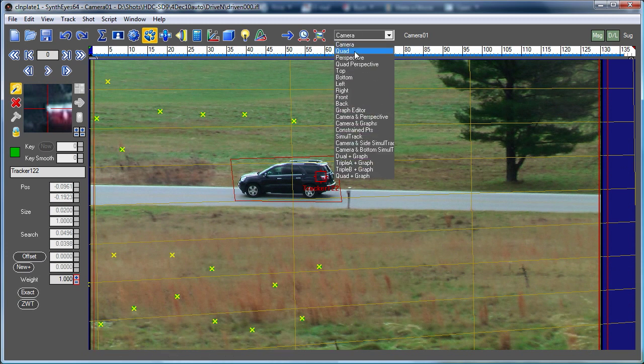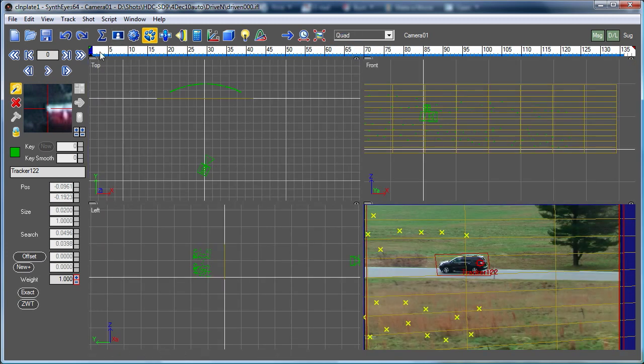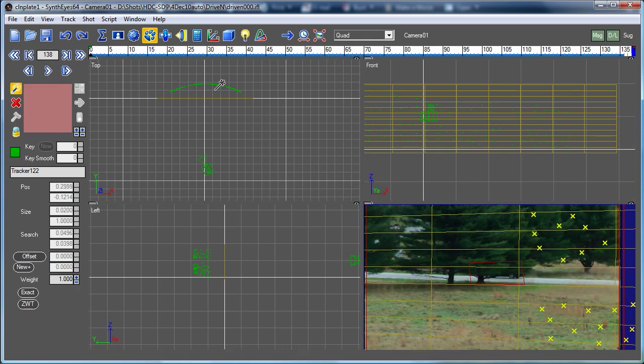Let's go take a look in the quad view. Here's the situation. We've got the camera moving. We've got this whole cloud of far trackers out there, and those are really just directions because we don't have any distances because this is just a tripod mode solve that we have due to the motion of the camera. And in front of those, there's a backdrop here, and that's what we computed in the first tutorial.